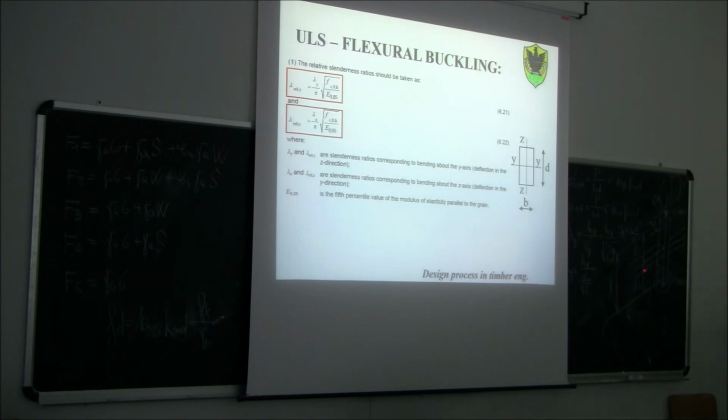So, the question is: is this beam across the column able to reduce the length when the column is going to buckle? Actually, we're talking about buckling around this axis here, so we're talking about buckling out of plane. This one is going to buckle in this way.